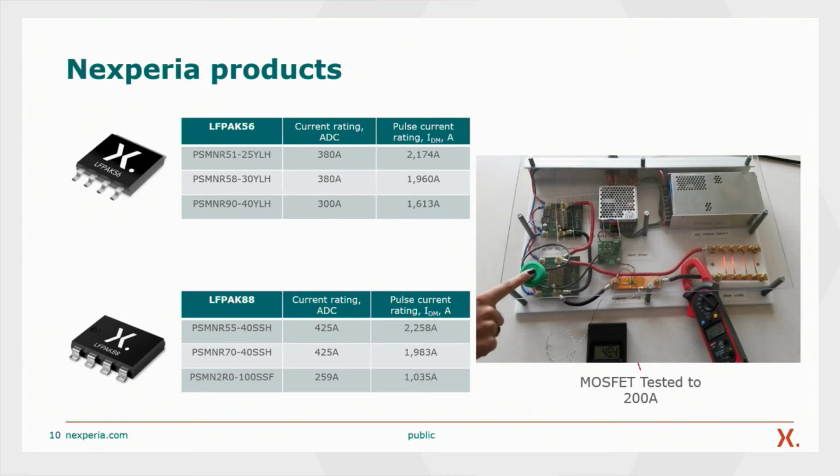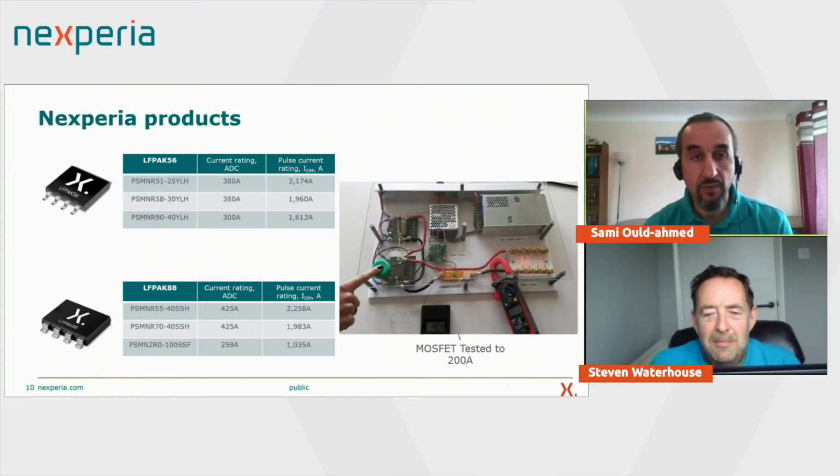So you can apply that, no problem. The challenge in real life application is maintaining that 25 degrees on the mounting base, and therefore care must be taken to always monitor that temperature. If it is very difficult to maintain, the recommendation is to make sure that your application caters for how much time you're allowed for that current to be through your PCB. But in a nutshell, provided these two conditions, the T junction is below 175 and the mounting base is maintained at 25 degrees, then that is continuous, and you can apply that on a DC basis.